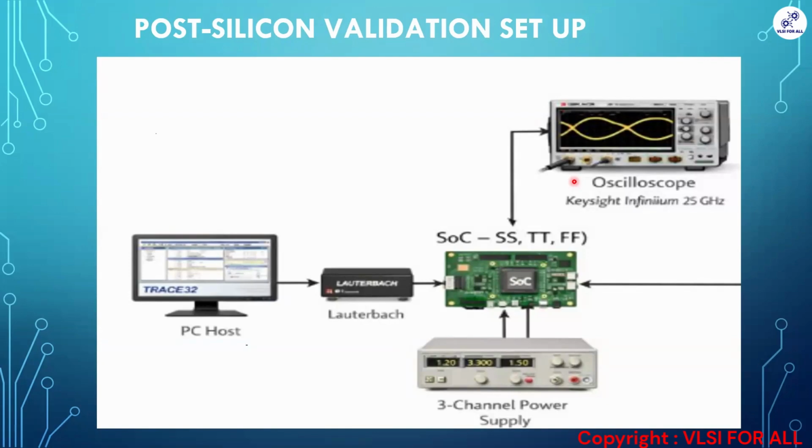And you should have a basic understanding of protocols if it is IP level validation for digital IPs, low speed or high speed. If it's analog IPs, it is different. Analog IPs will have PLL and ADC like that. So if you are given any IP, you should have an IP level understanding. What is the clock frequency of that IP? What are the data rates and how will that validation setup look? IP level validation and how to use hardware tools.